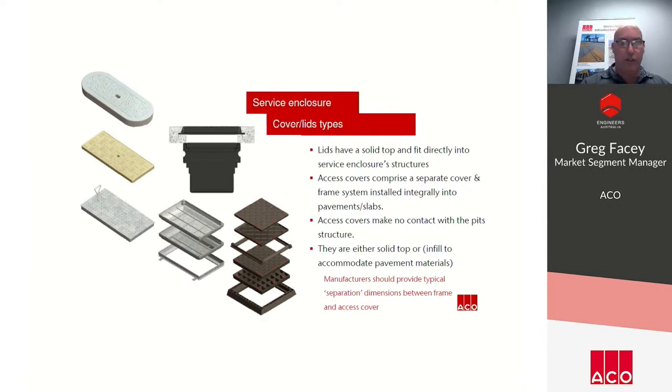It's also important to note that often iron covers may not be the exact clear opening dimension to that of the pit enclosure. The clear opening of the pit, though, must not be larger than the frame opening. The frame opening of the cover and frame system can be larger, but the pit can't, because it's important that the cover and frame system is fully supported with the surrounding slab.